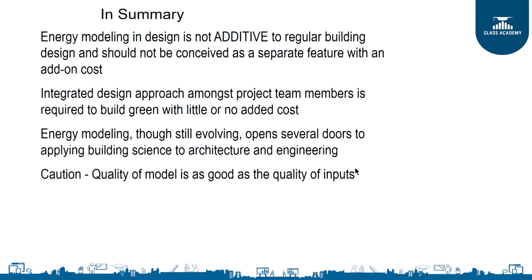So what happens is, throughout the life cycle of your building, this model is evolving and it's always calibrated to the actual performance. So tomorrow when you do an energy audit and you find certain energy conservation measures, you can put these measures into the model to see how much benefit you get, and you can start looking at cost benefit analysis and the percentage savings you will get. All those things can be done for every retrofit that you intend to do during the operations of the building. That makes it even more effective.